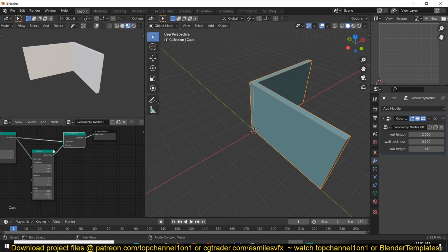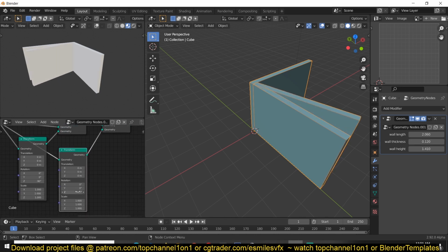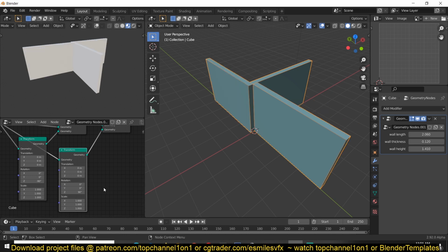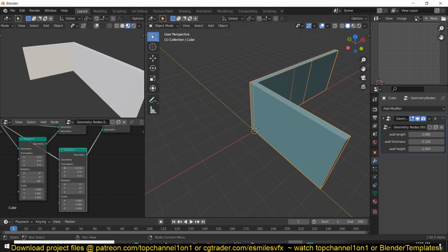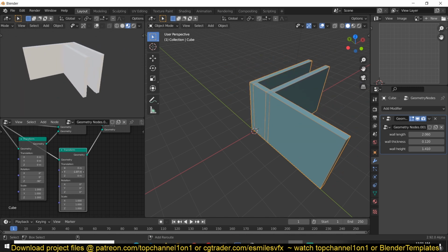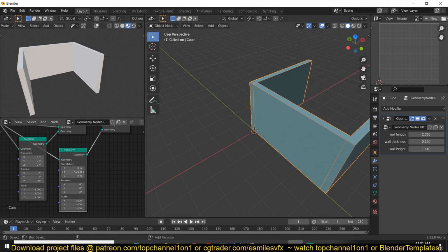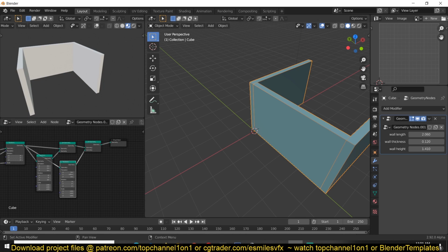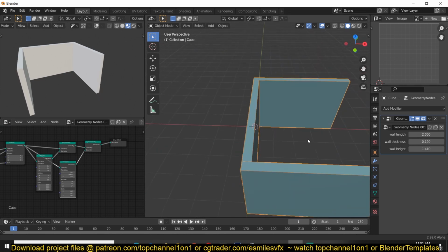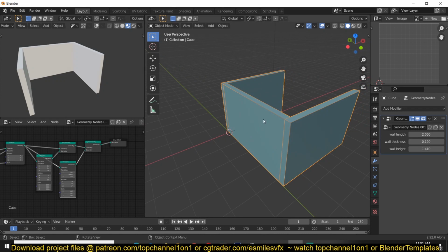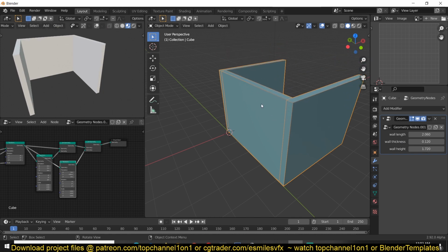and now we can duplicate this even further. So duplicate, still want the parameters to come in, duplicate that so that I can add this again. This time around we can rotate this 90 degrees, let's see, 0 degrees, yeah, 0 degrees, and just move this on the Y axis like that. And again, we can still control all the parameters. So we might need a few tweaks for the length to make this independent from this. We get that,